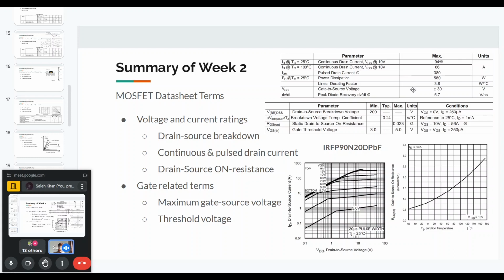we see in the forward characteristics or the output characteristics, after 12 volt or 15 volt, these curves are almost similar. If we increase the gate source voltage beyond 15 volts, there will be no advantage, we will not get a lower resistance. So that is why we will only go up to a maximum of 15 volt, or even 12 volt is sufficient. So even though the maximum allowable rating for the gate source is 30 volts, 10 or 12 volts will be sufficient.